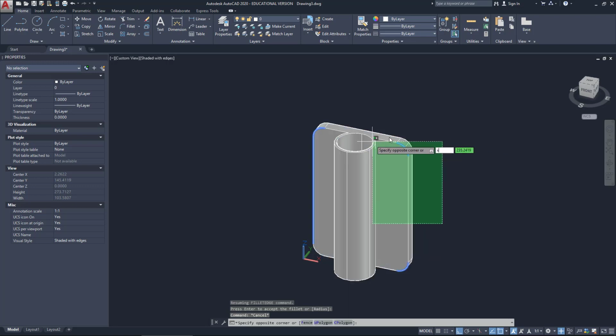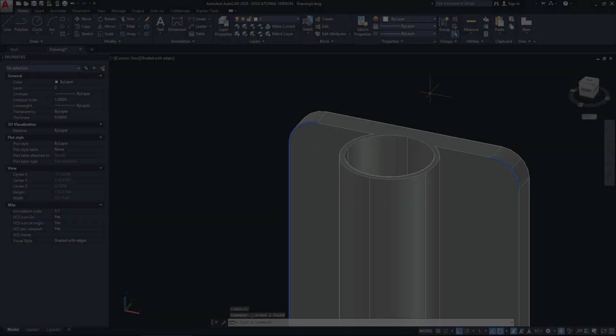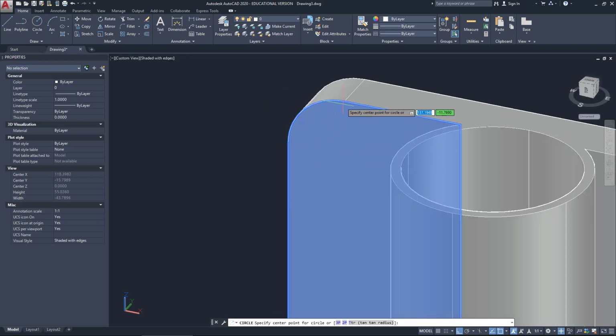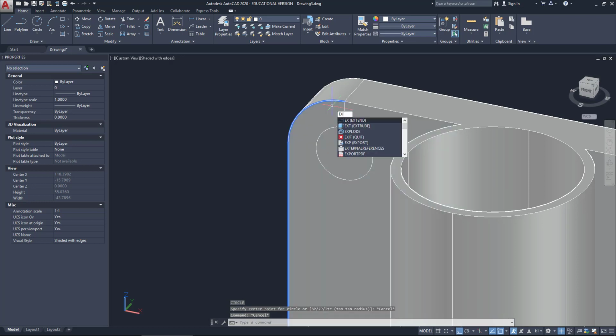So that's my object. I just need to put some holes in here. So I want to put a circle in. Let's see if I can put in a circle. I need to put it in the right location, which is just this point here. You'll notice when I go to there, it actually locates that point. Click, and you'll notice that it didn't actually give me the face of this object. Maybe what I need to do is to draw a line. I might find I can draw a line from here down to there, and then put a circle on that face. So I need to find that face, snap to that point, and this wants to be a 6 millimeter circle, or 1/4 of an inch. Enter. We're going to extrude that, and just escape, extrude.